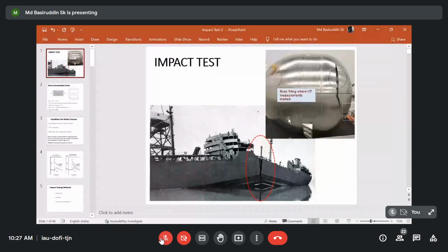But here in impact situations, if you think of the loading rate, then relatively it is very fast. So that is why, though the same amount of load in the tensile test results in the ductile kind of fracture, in impact conditions where you are applying a high strain rate, maybe the material fails in brittle fashion.